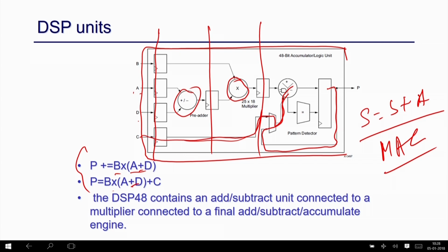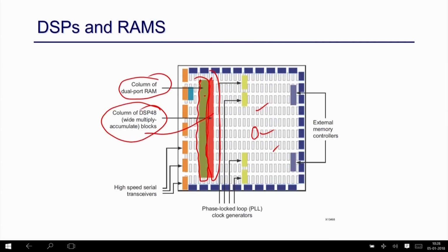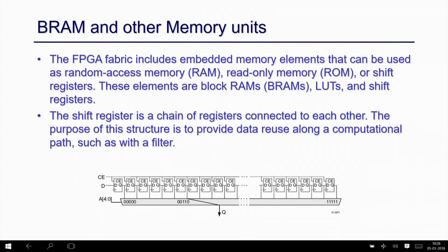And also you can pack some of the setup registers, 3 layers of registers are there. So it has 3 latency, either you can bypass or you can use them. So this is the abstract structure. In a design you can actually bypass any set of registers also. So this is what the DSPs have, and also it has some memories, RAM.